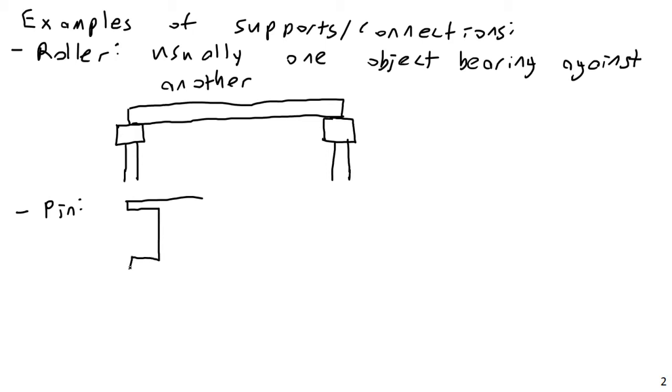So anyway, think of a W section. How does a W section work mechanically in terms of bending? What is the basic logic behind a W section? Why is it designed the way it is? Should hopefully remember this from mechanics of materials. Exactly. The whole idea of a W section is to maximize moment of inertia. You're trying to get as much of your cross-sectional area as far from your centroid as possible.